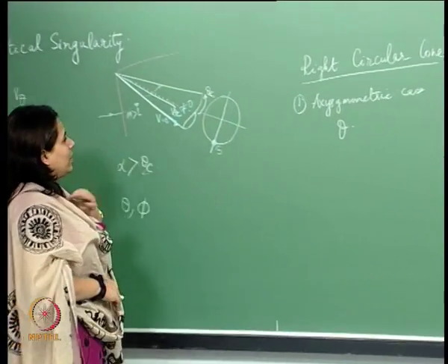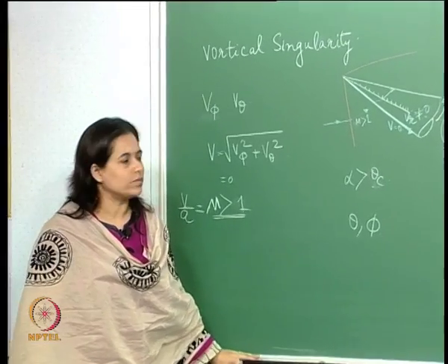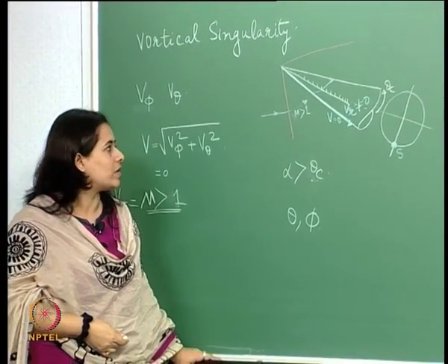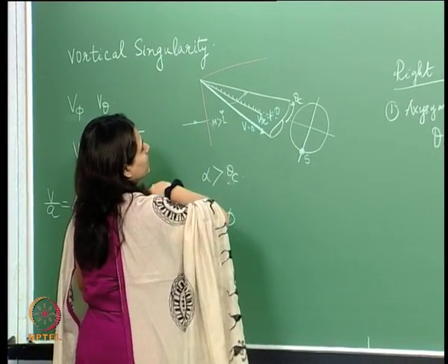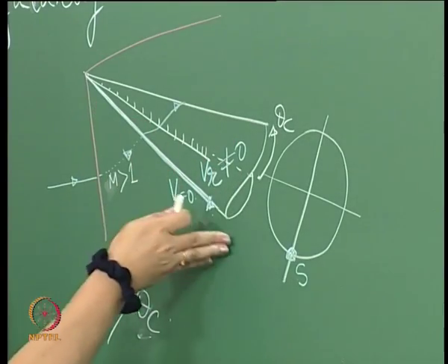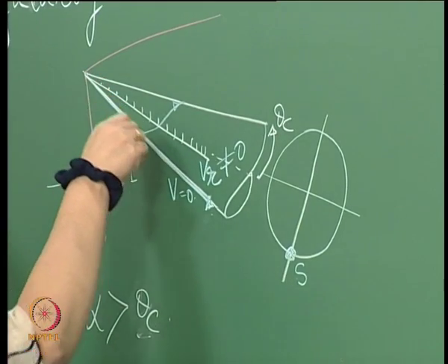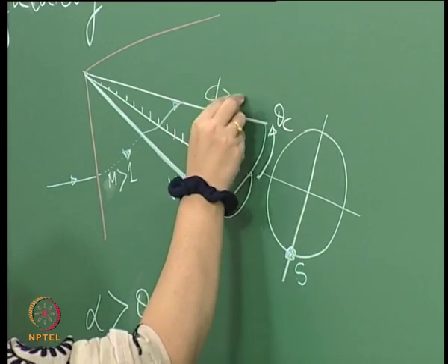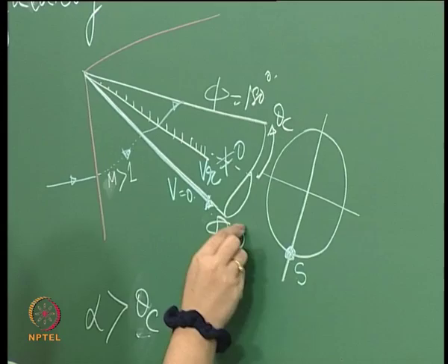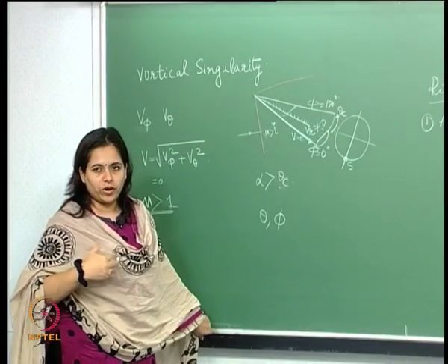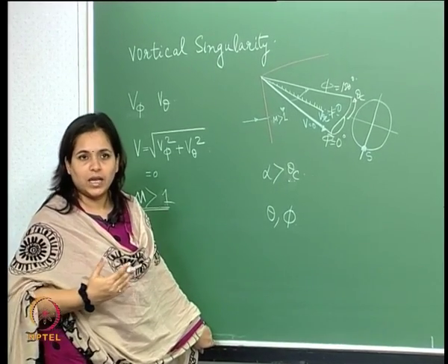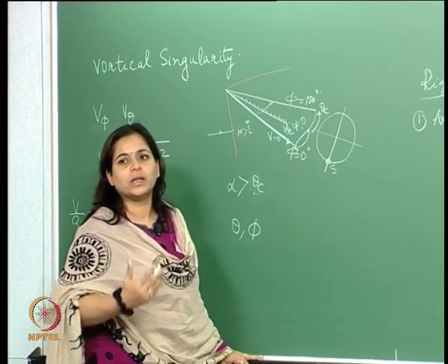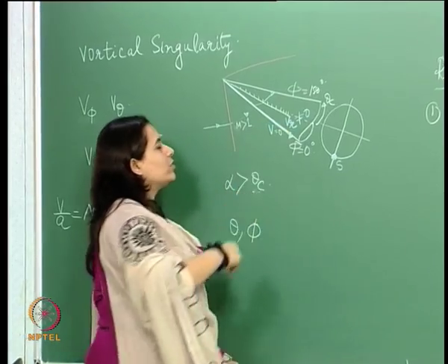Okay. One more thing before we close with this. Now, we've basically done an inviscid analysis over here. For this particular case, this is the right circular cone that we've been doing so far. The flow comes here, then it curls up and goes onto the leeward side of the cone. Let's call this 180 degrees. Here phi is 0. Now, experiments match our numerical findings from the inviscid analysis, because this portion here is also inviscid.